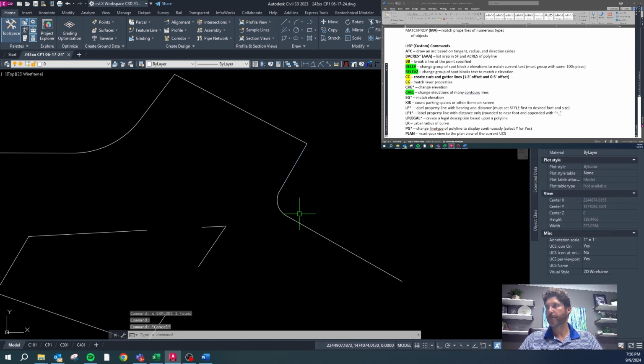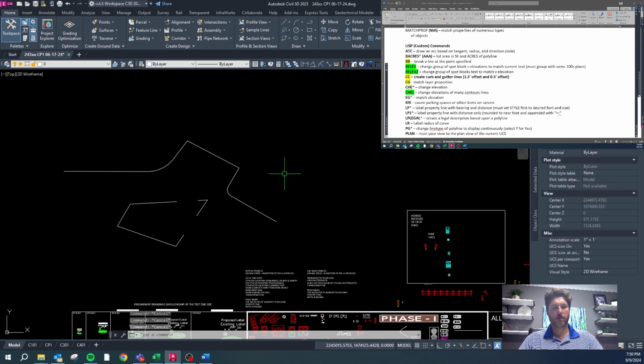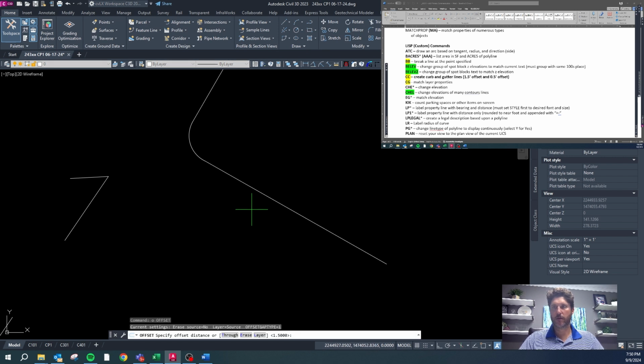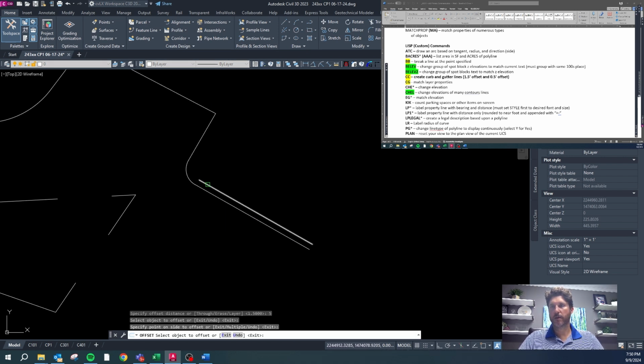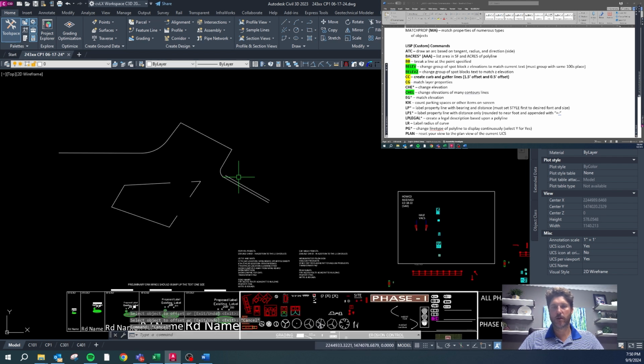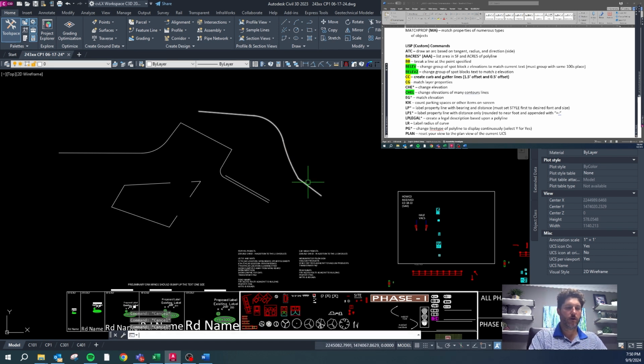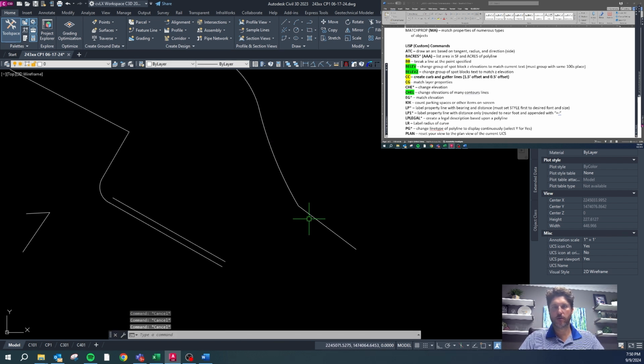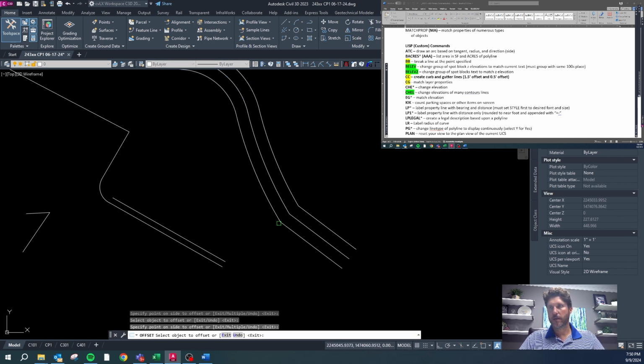and then you can explode this one and make changes anytime you want. We saw the offset command, offset 5, and I saw something interesting happen that I want to tell you about. So the offset command simply just offsets things, and if you have curves, that's fine. OG for offset gap type. OG is the quick key. You usually want to leave this off at 0. And when you do that, I'm going to hit O for offset again and pick 10. It just fillets this to a 0.